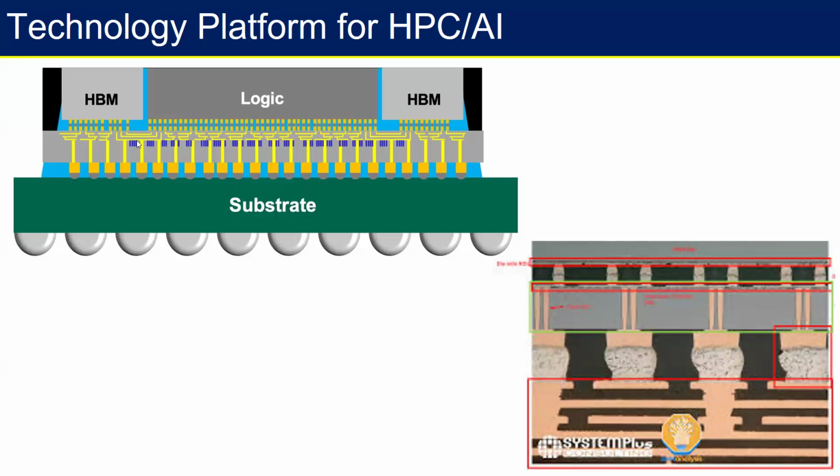And now this has to provide these internal connections between this logic and memory die. Okay, so this logic has to talk to memory not through the substrate, but through this interposer, which is typically made of silicon. Obviously, there are issues with that, and that's why TSMC has been actively working on replacing this interposer with some other materials. But as of now, most of the chips in the last generation, at least till Blackwell, were on an interposer of silicon.